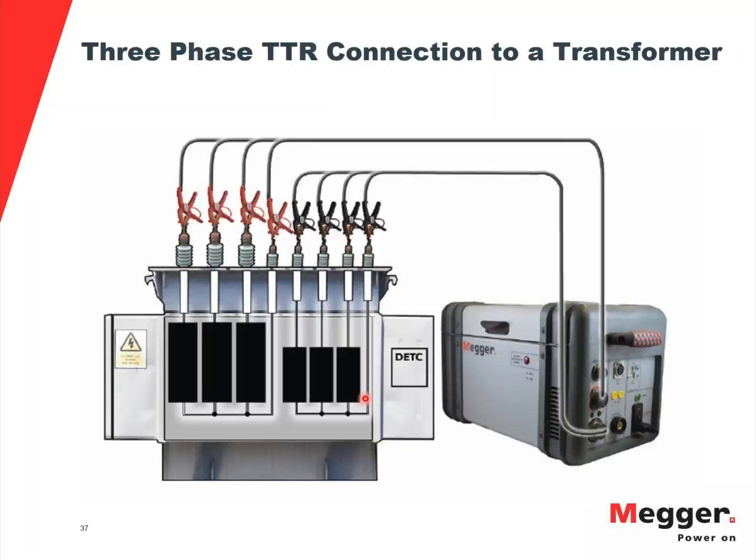And your extreme tap position should not deviate more than 0.5%. So those are the things I would keep an eye on when I'm testing an autotransformer. And if the autotransformer has a tertiary with a delta winding, I would be very careful when I'm doing the primary to tertiary turns ratio.